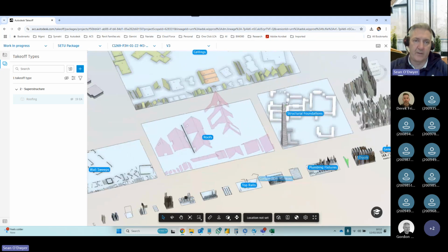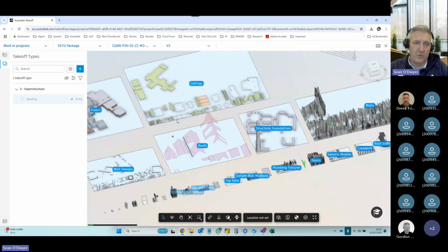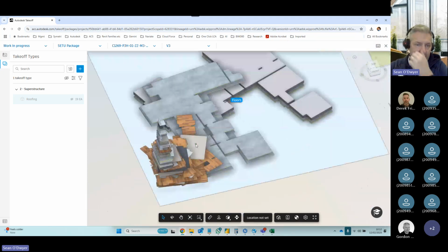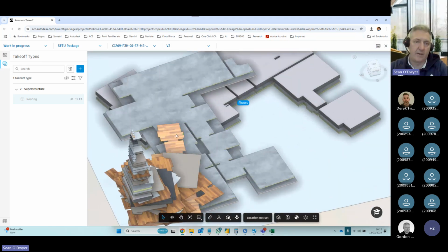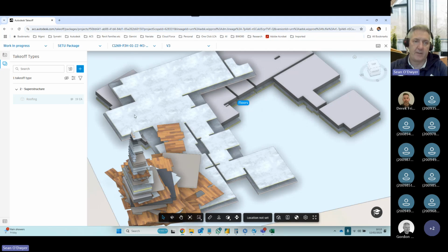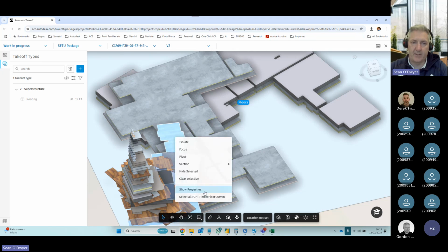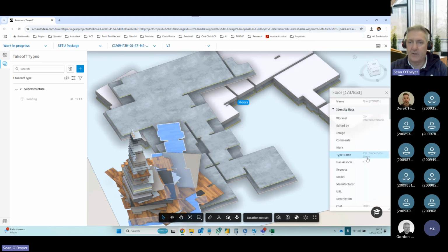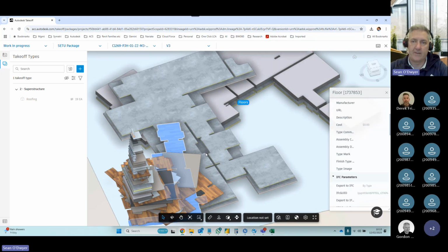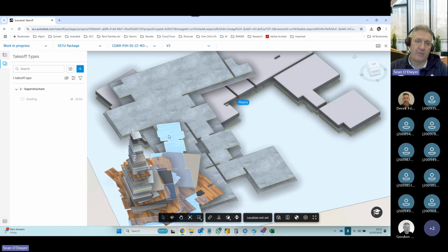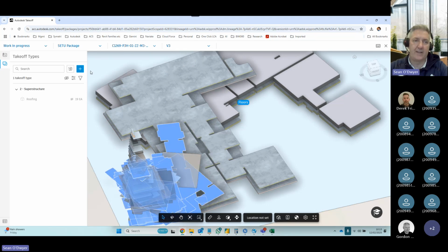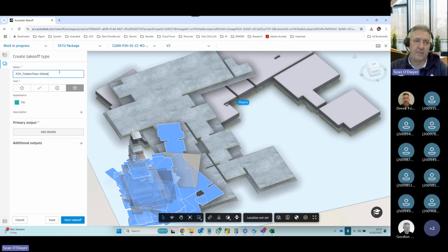You can also start going into other areas. And if I wanted to do, let's say, flooring, it's breaking everything into its floors here and it stacks them all up. So a quick way of doing that is if I want to capture this, so I just escape that. So if I want to select that, I can get the properties of that floor. So that is 220 millimeter timber flooring. To quickly capture that, you can right click it and go select all timber flooring, and you can add that in as a package. I'll just call that timber flooring.